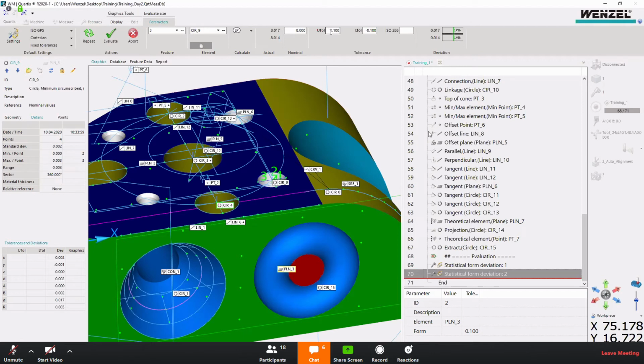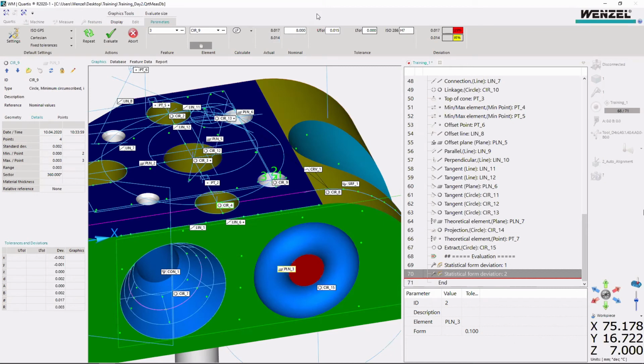And then this is the upper tolerance and lower tolerance. And then here is the ISO 286. It's like the fit dimensions, like H7 or H12, all these, how tight it is to be. So you just need to simply key in. And then this is an inner circle, so for the hole, this must be a capital H. But no worries, it will automatically adjust it for you. So it's very convenient. And then you will have 2 deviations also, because we have 2 actual values.